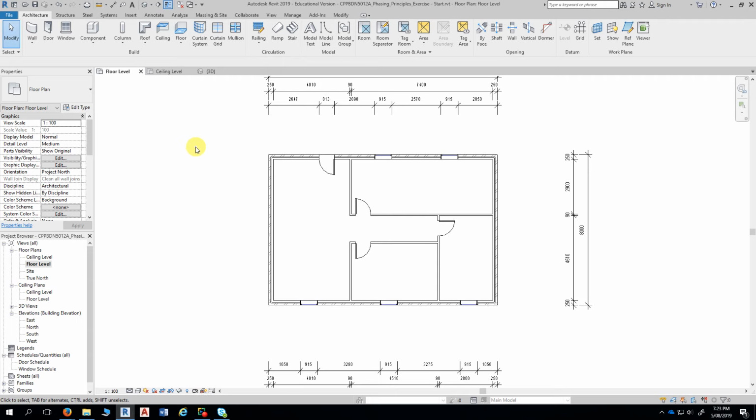Okay, so what's an underlay? What does that do? Graphic visibility? The underlay setting allows you to see what's on the level below or the level above. So it's not a visibility setting, although it does show us the roof. It's just showing us what's above, if there's anything above, and what's below, if there's anything below the current level. So that's the purpose of the underlay optional setting.